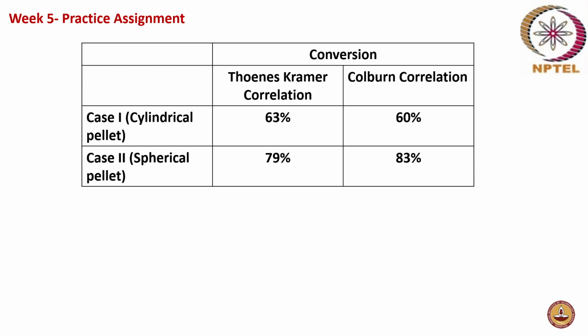This may be due to the major factor of the temperature, because you could find a drastic difference in the diffusion coefficient also, and there is a minor change in your porosity of the bed also. So increasing the velocity by 10 times really didn't help in conversion, right? We have to consider all the parameters while considering the conversion, because just increasing the superficial velocity to a greater extent may not help. It may be due to several other factors.